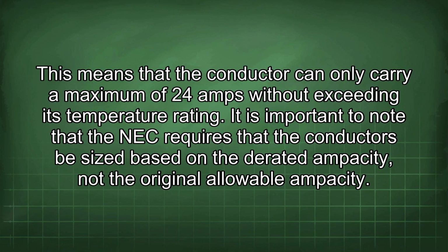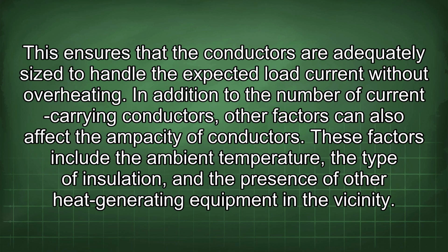It is important to note that the NEC requires that the conductors be sized based on the derated ampacity, not the original allowable ampacity. This ensures that the conductors are adequately sized to handle the expected load current without overheating. In addition to the number of current-carrying conductors, other factors can also affect the ampacity of conductors. These factors include the ambient temperature, the type of insulation, and the presence of other heat-generating equipment in the vicinity.